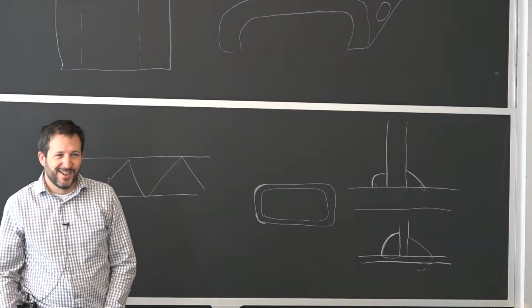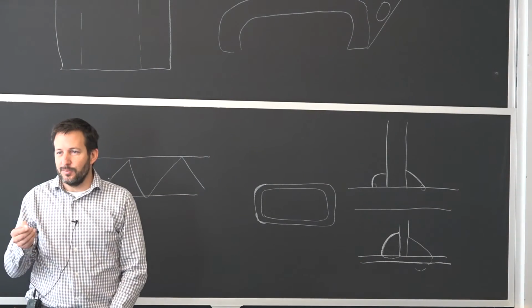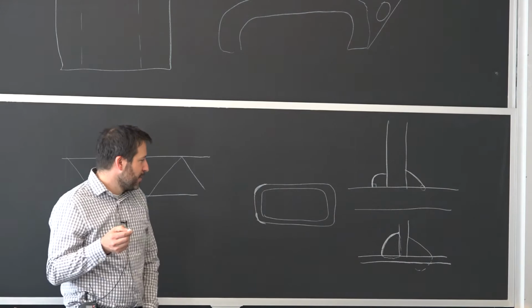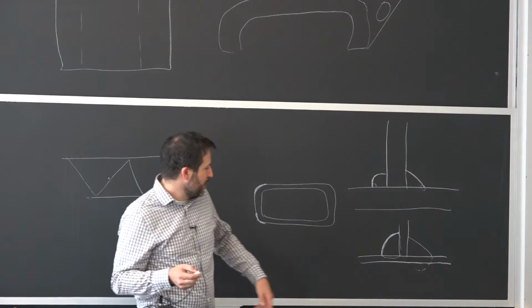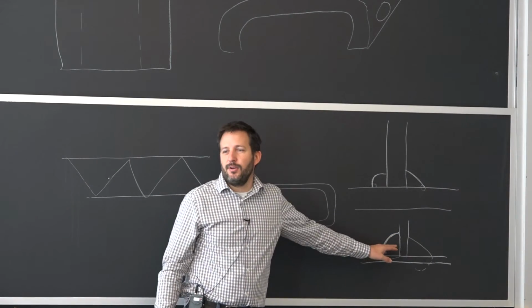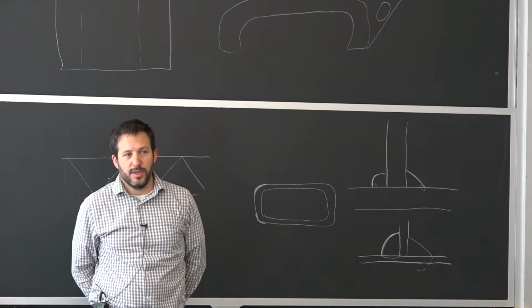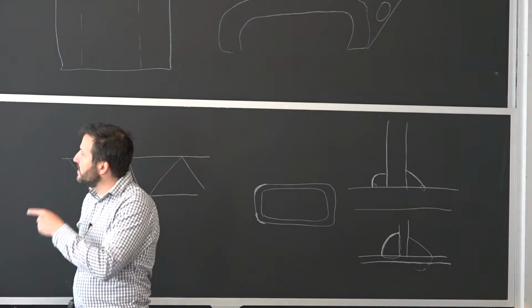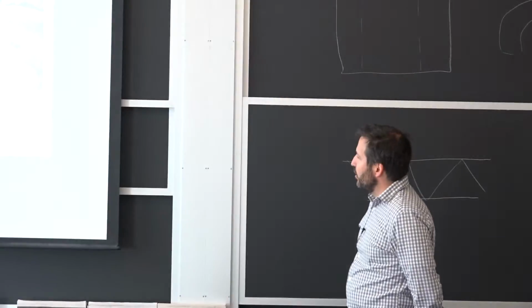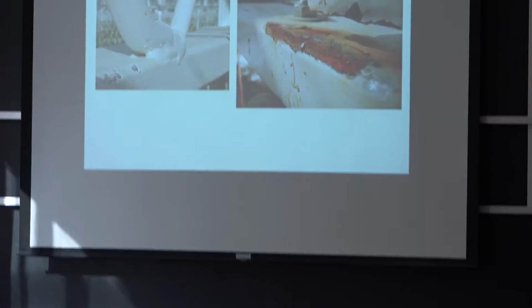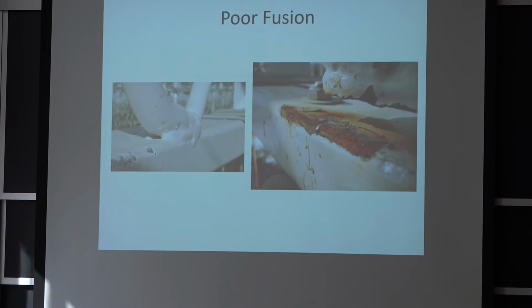So in automotive, that's one thing they do. They'll use processes that allow you to throw some metal and have limited fusion because you're all talking about sheet metal that's pretty thin. In this case here, it was a little bit intermediate. So the thickness of this member was, I think, 1/8 of an inch, so about half the bead size. So they had to be a little careful, but they should have put more heat.